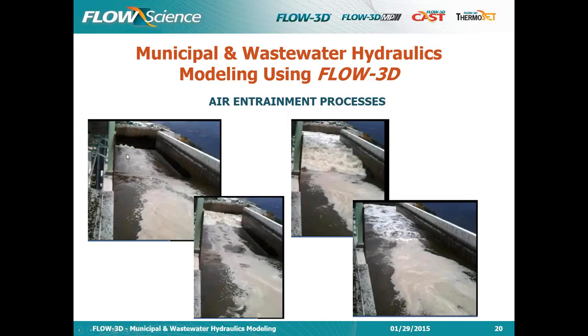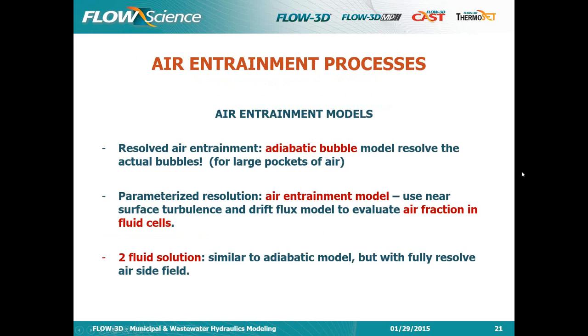And the problem we're having, I'll get back to this shortly, is that the bulking in the pipes is preventing the flume from working. In fact, the tank starts filling up. This is, I guess, time 2. The tank starts filling up, and there's a reverse flow back into the flume, and then it's completely flooded, and the whole thing becomes completely inoperational. So we'll get to that very shortly, but what tools do we have for air entrainment?